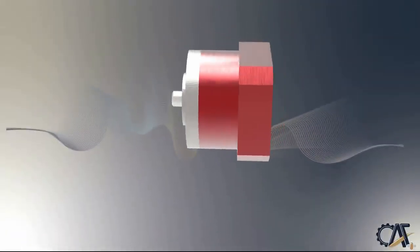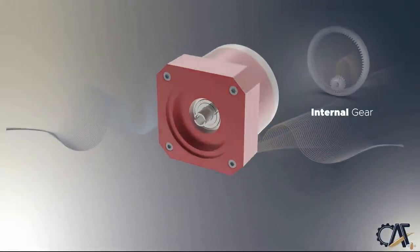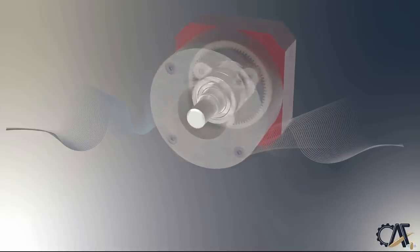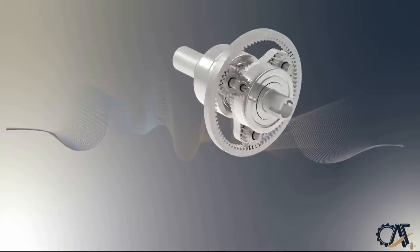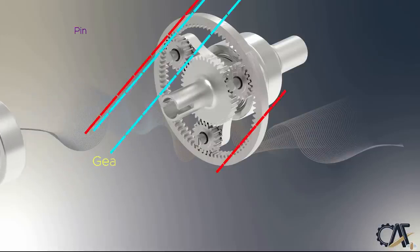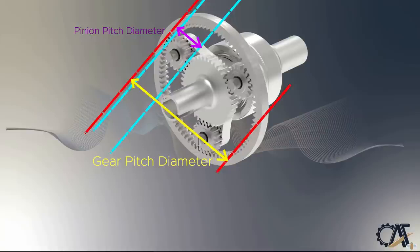One of the common places that internal or ring gears are used is planetary gears. Planetary gears are often used when space and weight are an issue, but a large amount of speed reduction and torque are needed. This requirement applies to a variety of industries, including tractors and construction equipment, where a large amount of torque is needed to drive the wheels. Other places you will find planetary gear sets include transmissions of helicopters, turbine engines, automatic transmissions, and even electric screwdrivers.